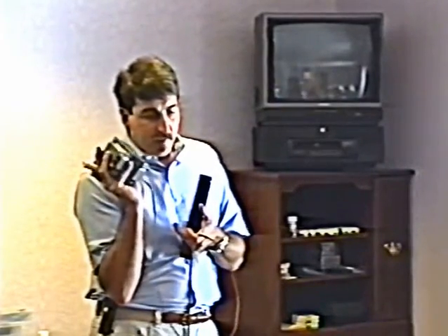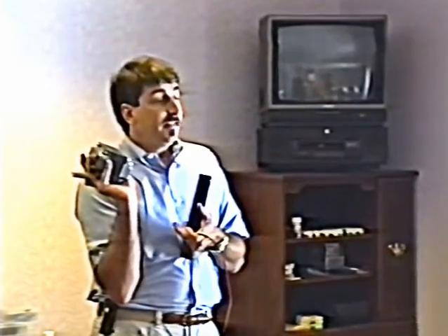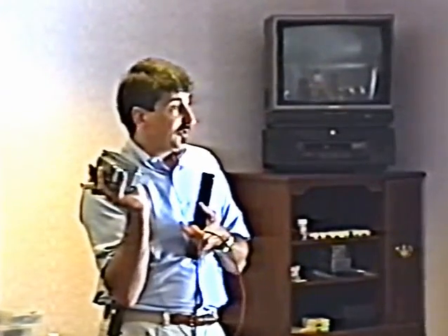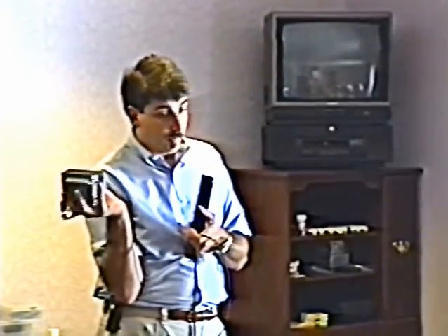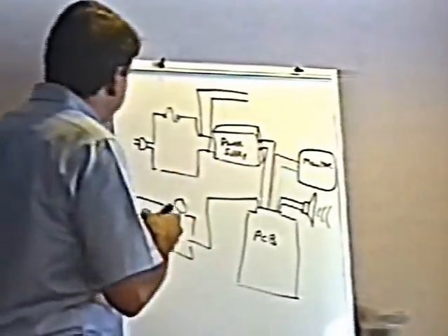Without the isolation transformer, the monitor will have 120 volts on the metal chassis of the monitor. Meaning that if you are grounded somehow and you touch the metal chassis, you shock the living daylights out of yourself, number one. Number two, if you actually ground the metal chassis of the monitor without the isolation transformer powering it, you just blow the snot out of it. You'll blow up the monitor, you run the risk of damaging the logic board, all kinds of stuff. So in every video game, there is an isolation transformer that's used strictly to power the monitor.